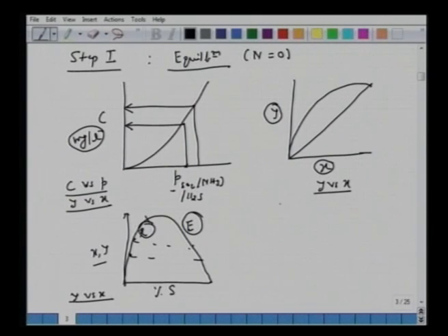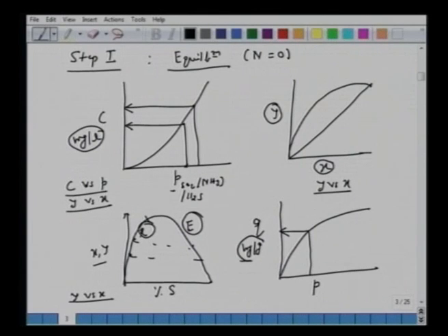Okay, then we talked of Langmuir isotherms. Given partial pressure in one phase, what is loading Q, milligram per gram? So given partial pressure in the gas phase, how much CO2 or sulfur dioxide will be absorbed to give this loading. Or even in the aqueous phase, we can say given so much concentration C aqueous, how much is the loading of fluoride or arsenic on certain materials. So these are the 4 unit operations where we talked about this equilibrium from thermodynamics.